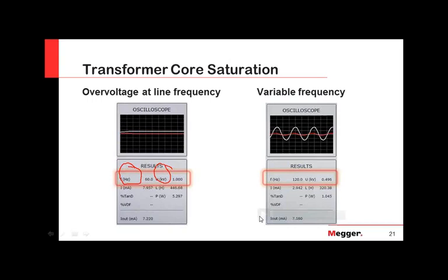What's going to happen here is that, using the power factor test set, the Delta 4000 instrument, I was able to apply different frequencies to the same specimen. In this case, you can see that we're applying 120 hertz. We're already at 3 kV. Again, the red sinusoidal corresponds to voltage, the white sinusoidal corresponds to current.